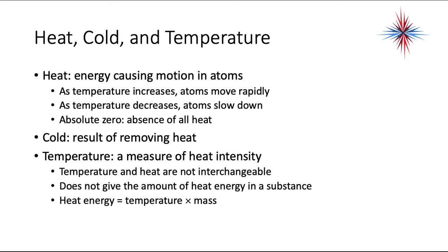Okay? Cold, result of removing heat. To make things cold, we have to remove heat. That's a pretty important concept. Temperature is a measure of heat intensity. Temperature and heat are not interchangeable. It does not give the amount of heat energy in the substance.